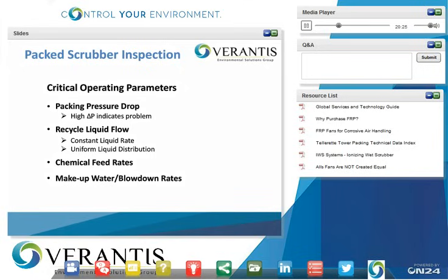And lastly, makeup water and blowdown rates. As much as people would like to have scrubbers designed with no water usage and no discharge, it's not possible. You have to be able to remove a small amount of the contaminants that you're producing, depending on the application. And the way that's done is by adding makeup water to the system. The makeup water also helps adjust for evaporative losses if the gas that's coming into the scrubber is not fully saturated.